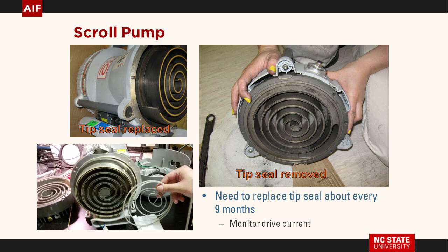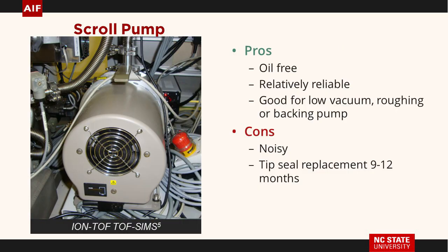So here's your tip seal replacement. There it is replaced. You can see it inside of it. Normally the ones we have last around a year. Oil-free, reliable, has taken over as your roughing pump. Can be very noisy. Have to replace the tip seals.